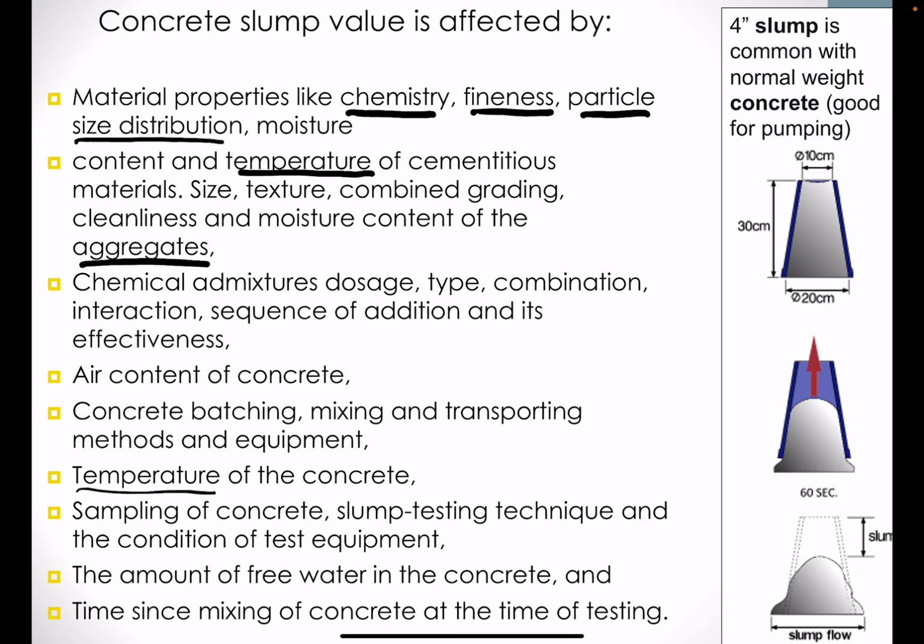And again, that displacement from the shape of the cone, the offset from that shape of the cone, is how we assess slump. So again, the slump value is typically listed in units of inches. So this 4-inch slump target is known to be a typical target to ensure that one can work with the material under a pumping condition, which is one of the more universally applied methods of applying concrete.